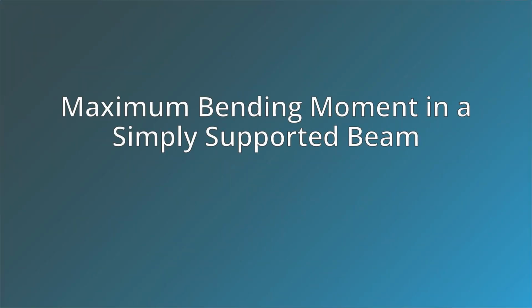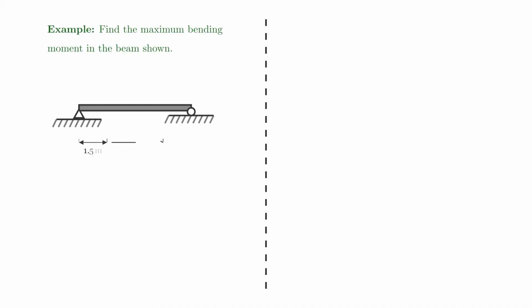In this video, we're going to be finding the maximum bending moment in a simply supported beam. In this example, we're drawing a shear force diagram and bending moment diagram for a simply supported beam with point loads. So the first step is to find the support reactions.